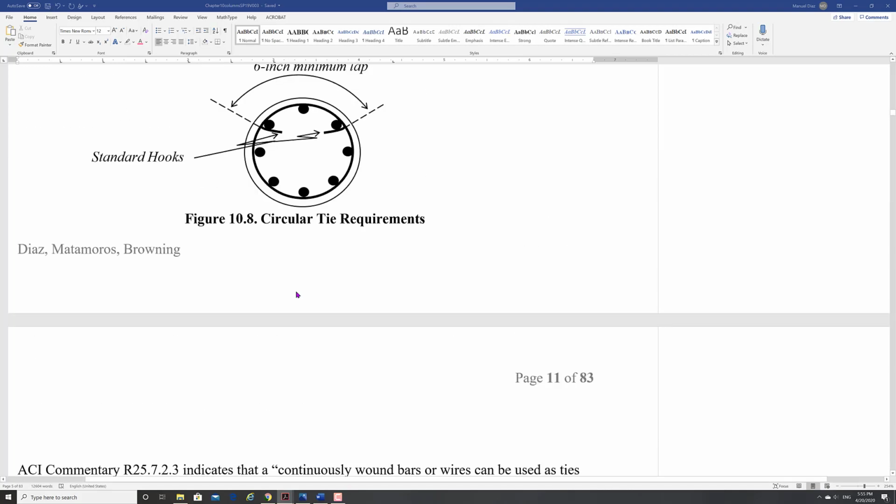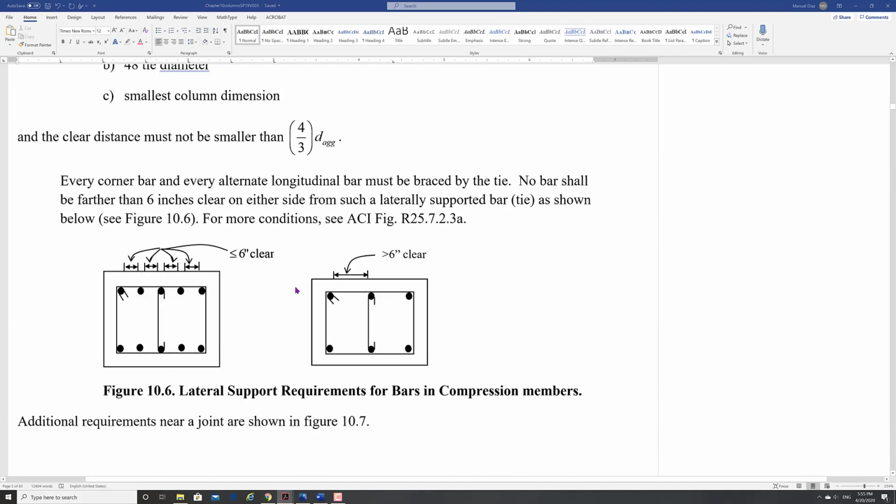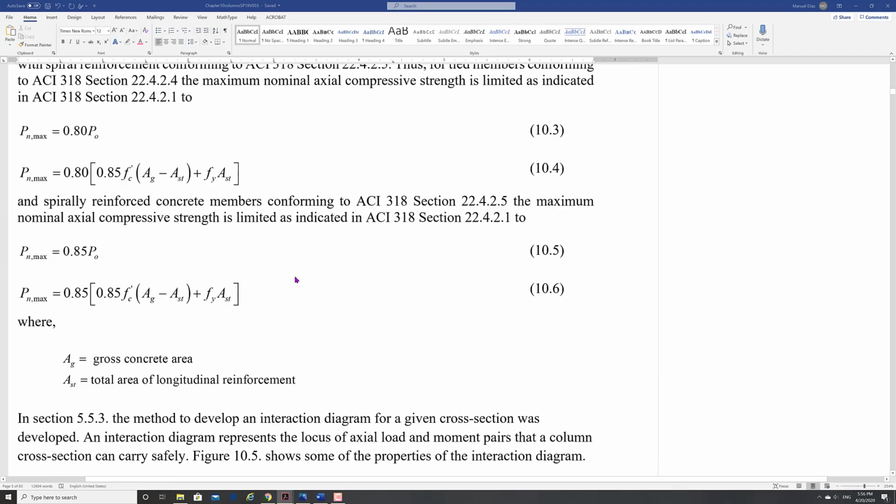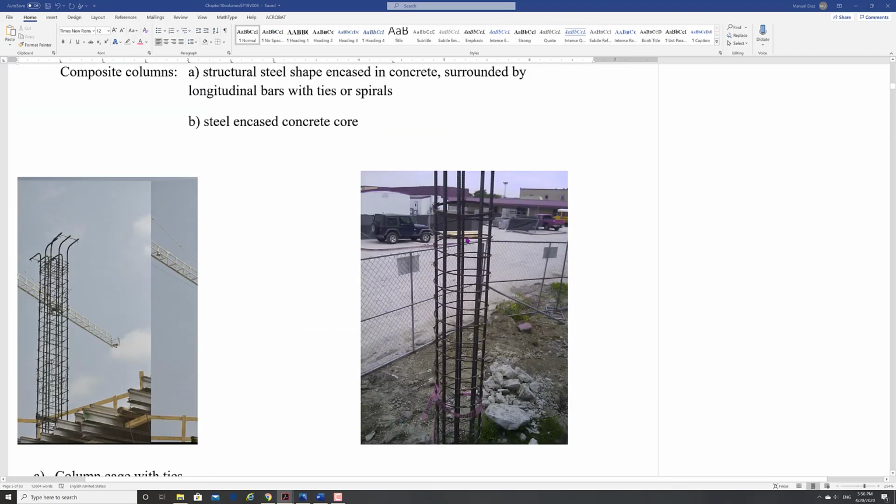And also at the end, when you get to the top, at the ends of the spiral, I don't know if this shows that. This one doesn't show here, but you had to go like right here. So you see kind of double bars, right? You are required to do that kind of turn there, okay? Right at the ends, you had to do like going around it, okay? So that's for the spirals.